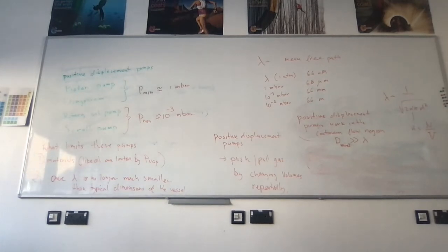So at this point, we could say, okay, let's just limit pumping to 10 to the minus 3. That's what we could do, and that's fine for a lot of applications. But you remember when we were talking in one of the previous lessons, for a lot of applications, that's rubbish vacuum, okay? The amount of molecules which is going to contaminate your sample is huge. If you're trying to build a device in the semiconductor industry, you're going to end up with a horrible chip. If you do surface chemistry, you can't do surface chemistry at these pressures. There's a lot of things you can't do.